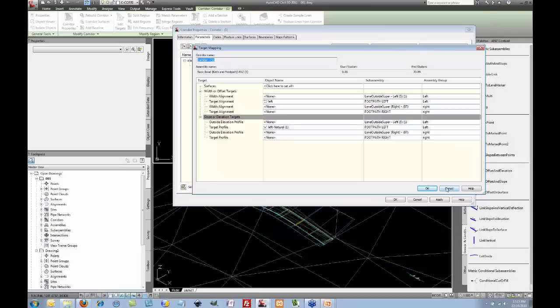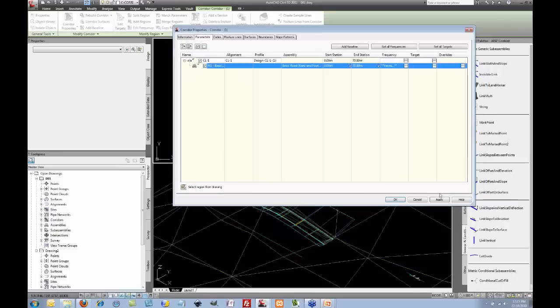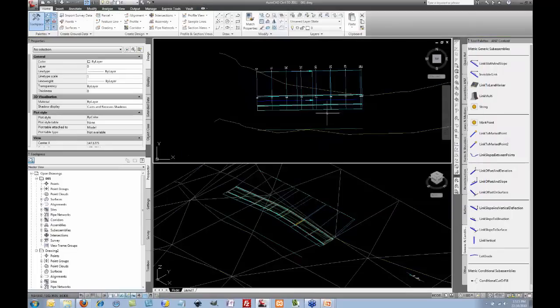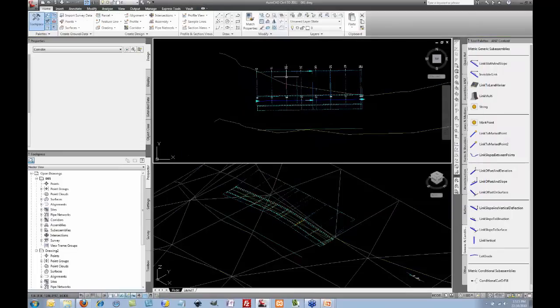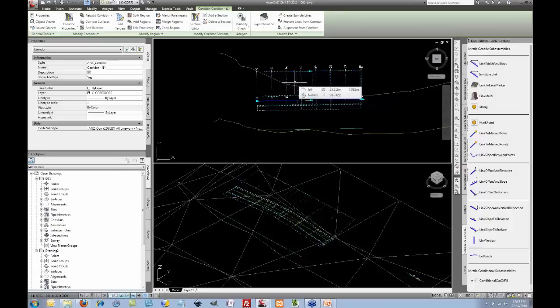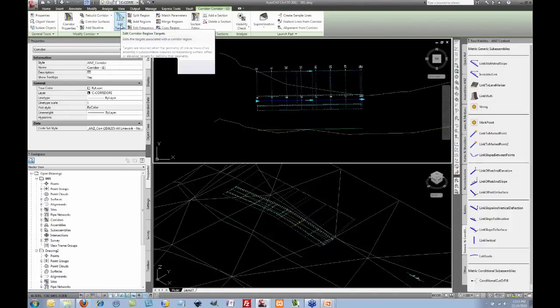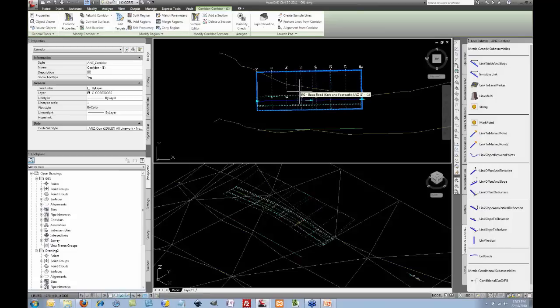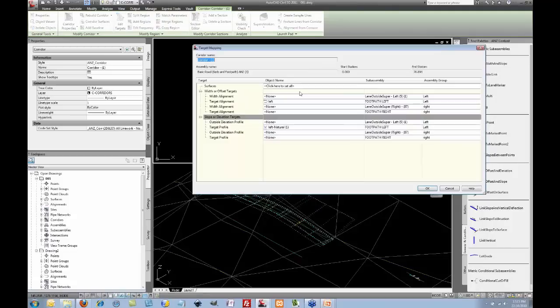So you should now see that. I think the connection here mightn't be the fastest, but what you now see is the map targets dialog box. On 2011, you can get to it in a much quicker way. So you highlight the corridor model, you press edit targets, and you always pick your change range on plan view in case you've got multiple baselines set up, and it brings you straight to that dialog box. You just bypass a few clicks.